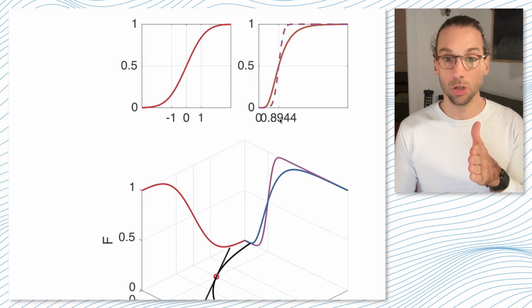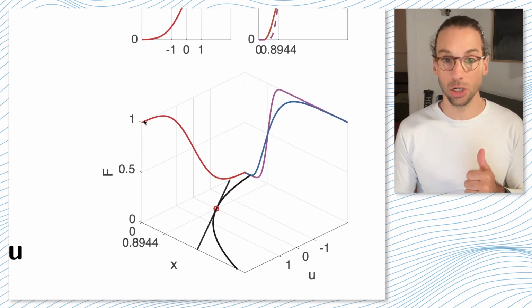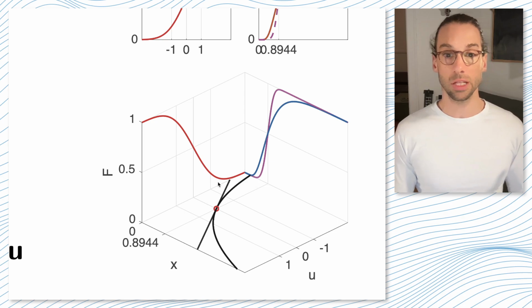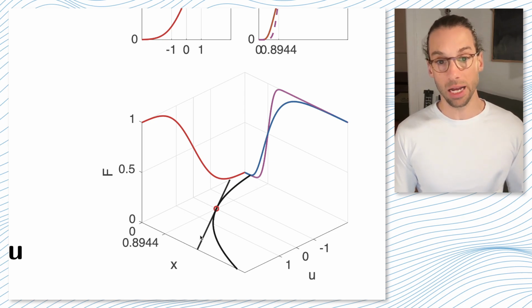Now if we plot the same relation here in a 3D graph, we have our standard normal CDF, we have our original CDF in blue, and the relationship between these two through the equality of the CDF gives me this nonlinear relationship. So what we're going to do is linearize that transformation at the design point here.